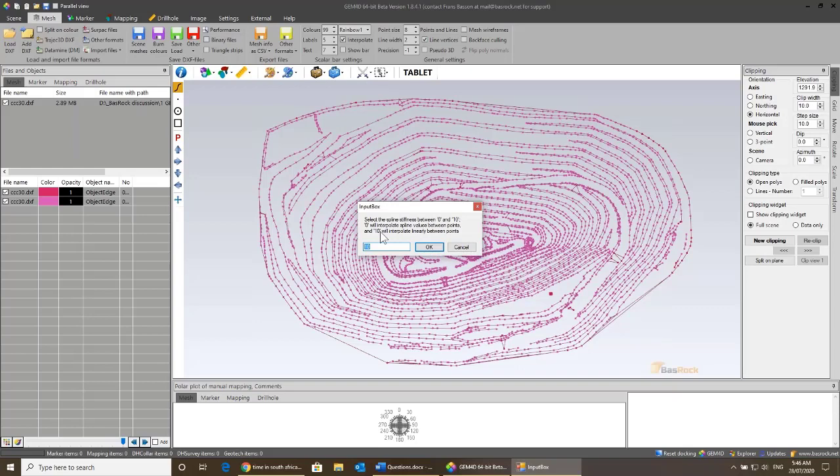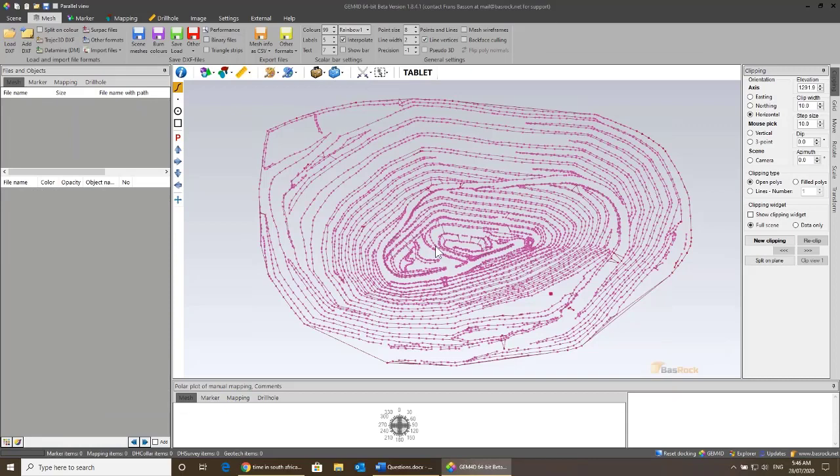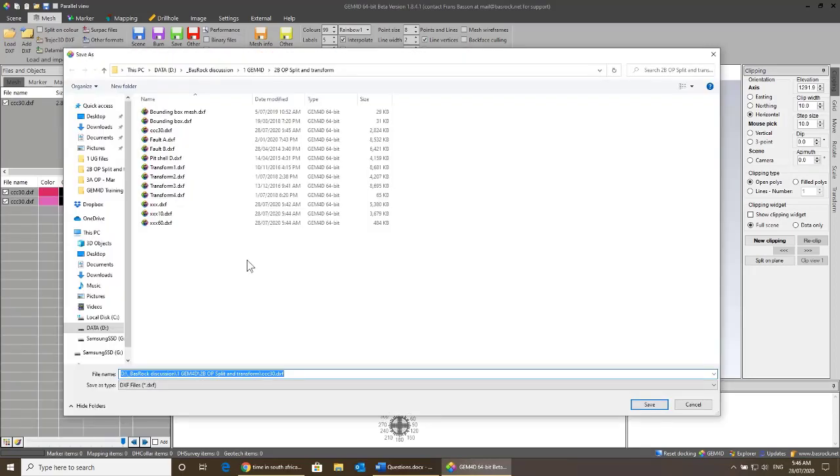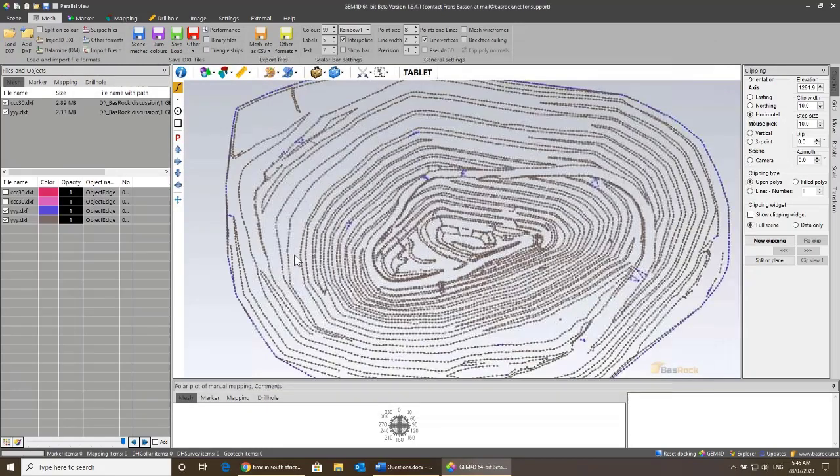So when you do that extrapolation of the line, it's going to use something called splines. And a spline is a bendy thing. But if you make it a spline of 10, it's actually a very stiff spline. It's basically a straight line. So I'm going to use the default. And I'm going to call this, let's call it YYY. And you can see the difference from the previous one.